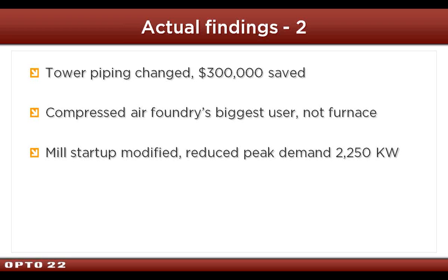We put the screen of the PC on the desk of the operator, and by watching their peak demand and staging the startup and the shutdown, he cut their monthly peak demand 2,250 kW. 2,250 kW was being wasted every month just because of their startup procedures.